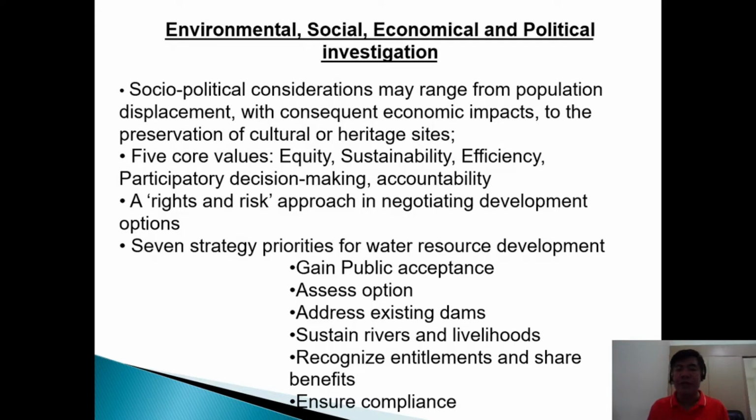So there should be one that will be looking into the environmental effect of the project, whether you have designed it very well, the slope stability is very safe, seepage analysis is within the tolerable limits, the foundation design is all well calculated, and in terms of the structural stability, it is all safe.